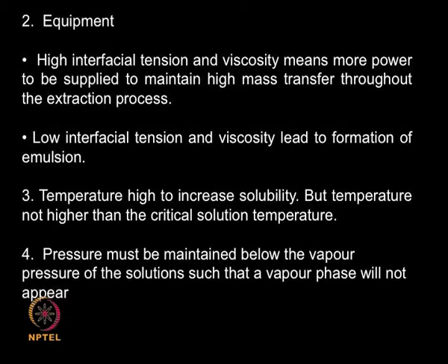Temperature, if I increase the temperature, solubility of the phases also increases, but I do not want to increase the temperature so much that it comes closer to the critical solution temperature. Pressure, I should maintain the pressure below the vapor pressure of the solution, otherwise I do not want the solvent becoming vapor or some of the feed components becoming vapor.